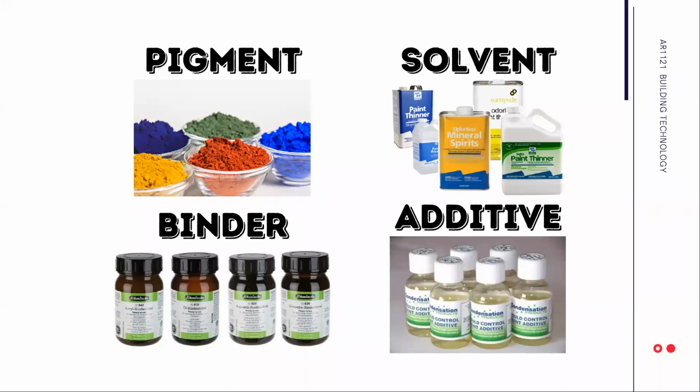Binders work to bind the pigment together and create the paint film. Binders are ingredients that provide a binding effect that holds the pigments together to create a dry film on the surface. A paint binder is a key ingredient that directly relates to the performance of paint, including adhesion, washability, scrub resistance, fade resistance, and gloss retention. Solvents are the liquids that suspend the ingredients and allow you to place the paint on the surfaces. Combining the pigments and binders, considered solids, with the liquids creates the paint coating you see in the paint can.